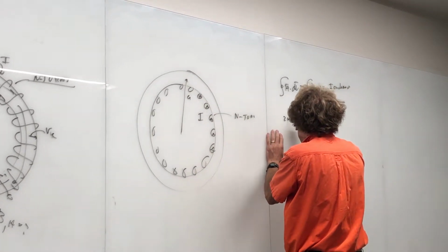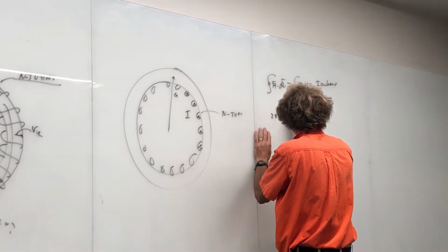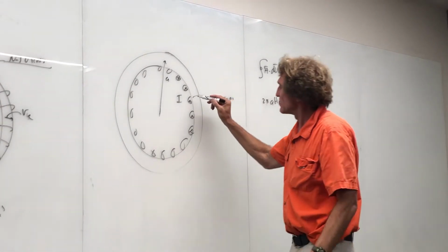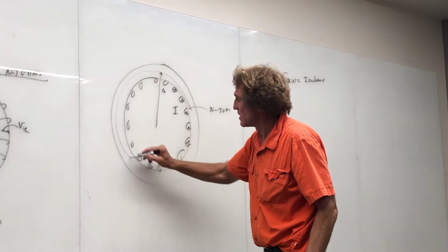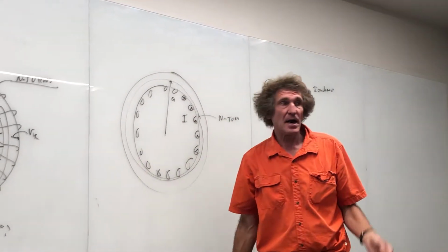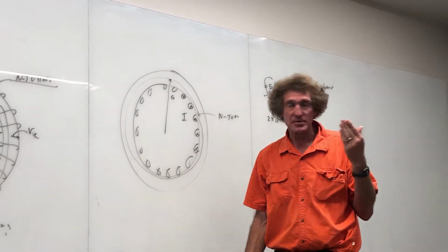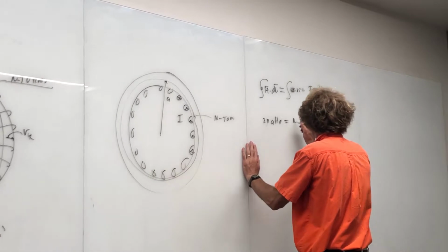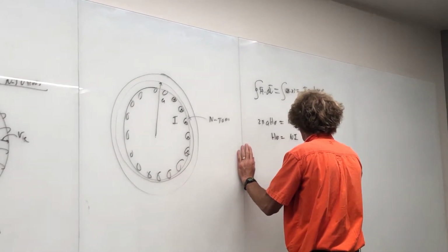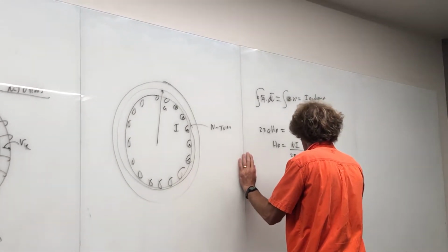So it's 2 pi A times H phi is equal to the current enclosed. But how much current is enclosed in this, my Amperian path? Can you all see it? How much? It's not I, what is it? N times I, right? Because I have N turns. So it's going to be N I. And that means H phi would be equal to N times I over 2 pi A. It would be in the A phi direction, but it won't matter.